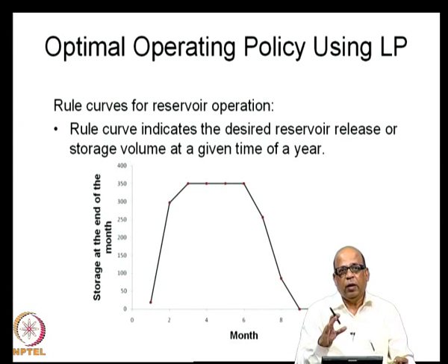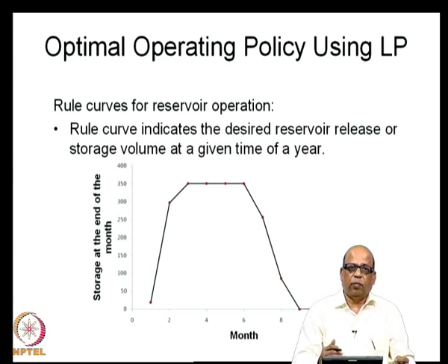I will repeat, you formulate the optimization problem with a certain objective function that reflects the objectives of your reservoir operation, solve the optimization problem, you will get the storages as well as the releases in general, and then formulate the policy of maintaining the reservoir storages at the end of the time period across different time periods within a year.